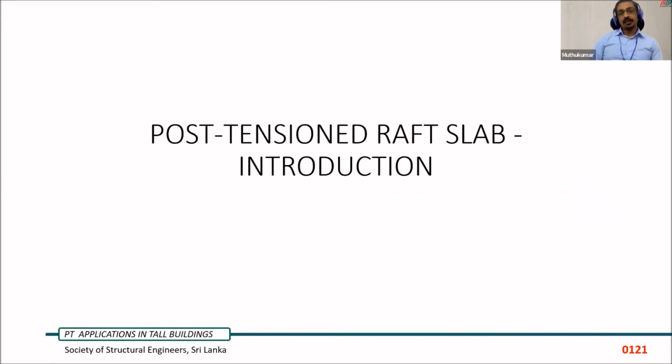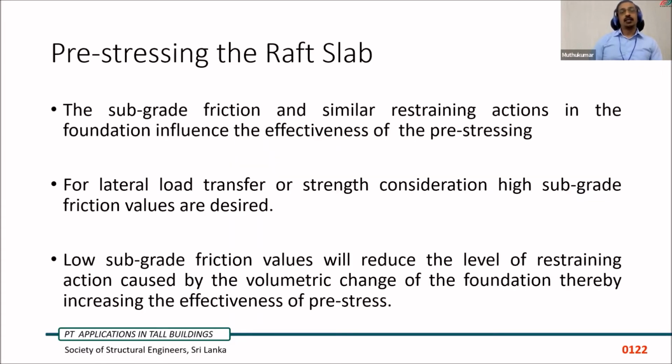And a brief introduction to raft slab. Normally PT in raft slab is not so conducive. However, in certain projects, when there is a requirement, this option has been looked at. The subgrade friction and restraining action is a major factor which keeps us away from using pre-stressing in raft slab. As I stated earlier, there will be a lot of huge restraint.